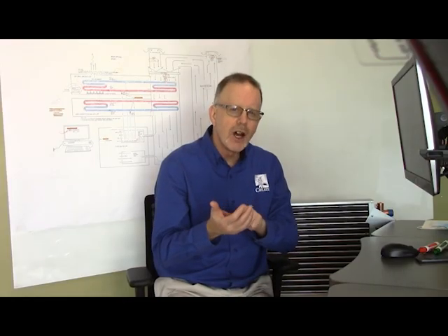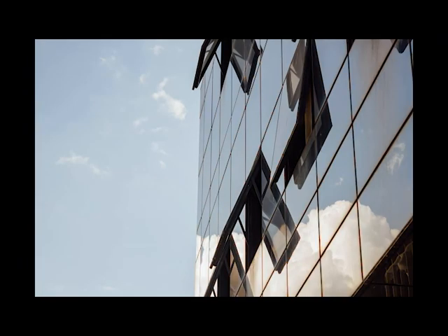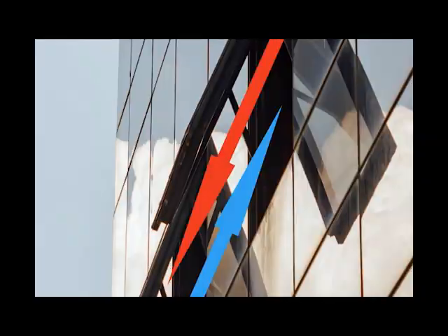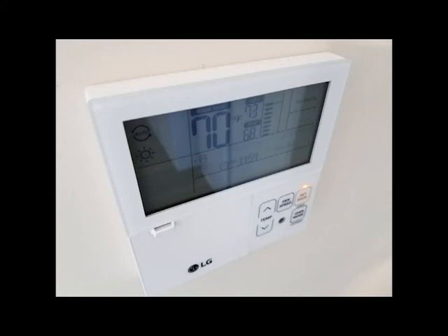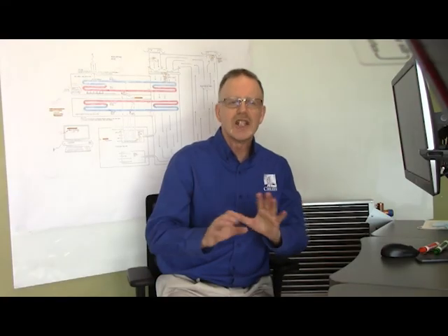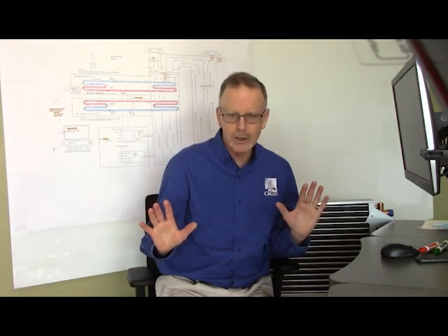Something should be pointed out here that should now be easy for you to understand. What will happen if the room space we've just talked about has a window that's been left open to the outdoors? As heat leaves through the window and cold air enters, the room space will be constantly calling for and receiving booster heat that isn't needed. This is extremely wasteful.